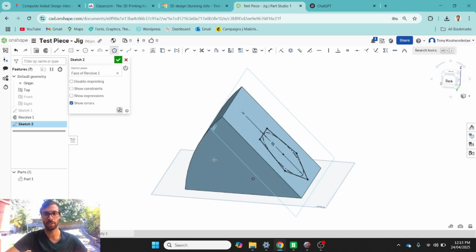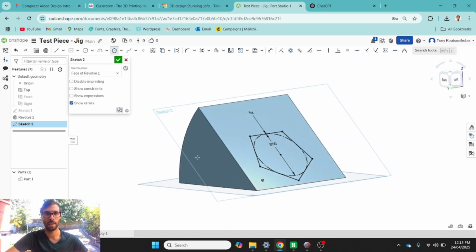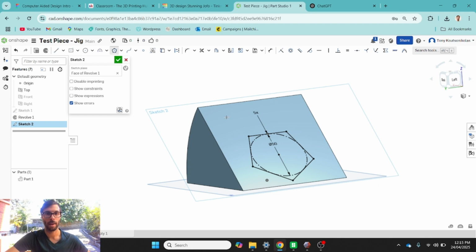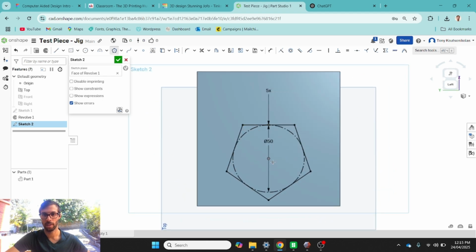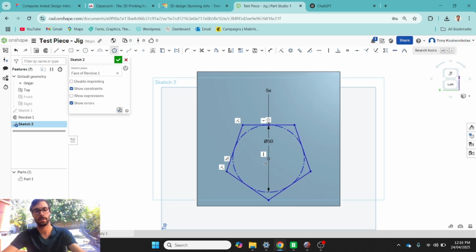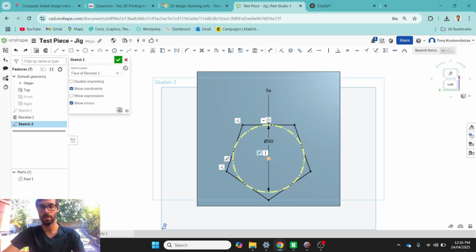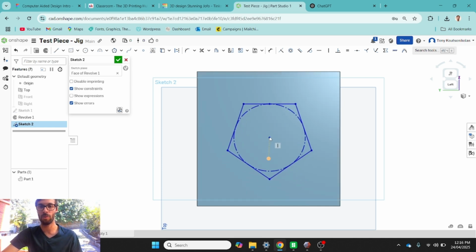And so now I've got a sketch of my part kind of cut out. But I'm not done with that. If I view back to sketch normal, now I've created a relationship here between these features, and you can see that my part is black. I'm going to show constraints, and you can see that it's got all these features here. These are relationships between the drawings. So this line and this point are connected. If I delete that, I can now move this in space.